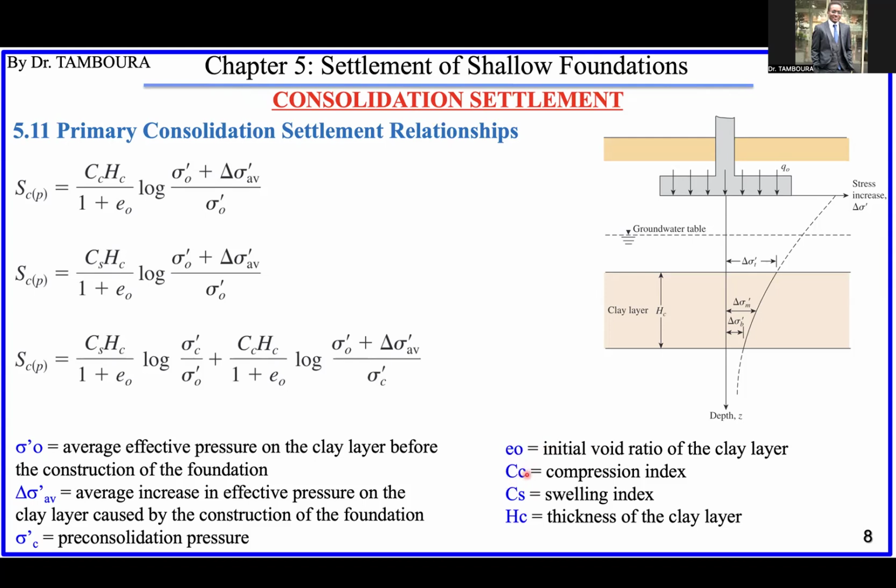Compression index also, we did it in chapter 1. Or go back to soil mechanics 1, you will see that after doing the lab test, the curve can give you the compression index and swelling index also. Hc is just the thickness of the clay layer. So let's go back to this equation one by one. This first one